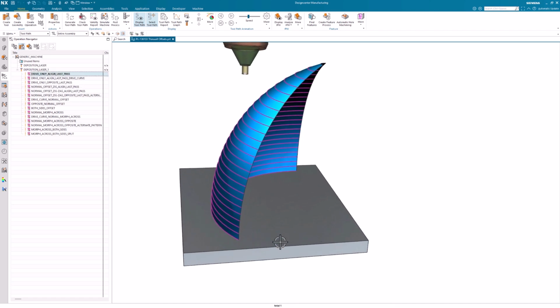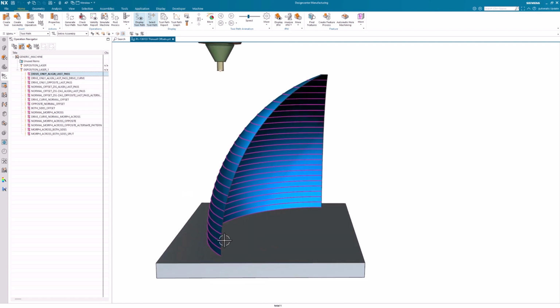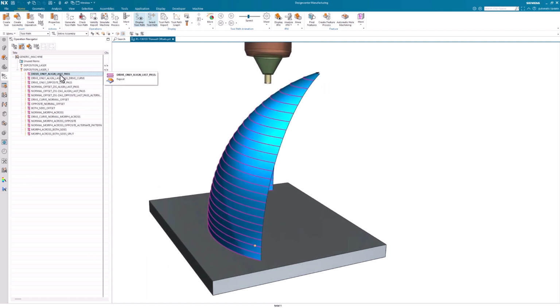Previously, programmers could only make one bead width on Thinwall faces. If they wished for a thicker part, they had to offset the face, create multiple operations for each offset face, then merge the operations together. Enhancements to 3D Freeform Thinwall buildup create an improved user experience by automating this process, so the user is not required to create additional faces and operations to get a thicker part.